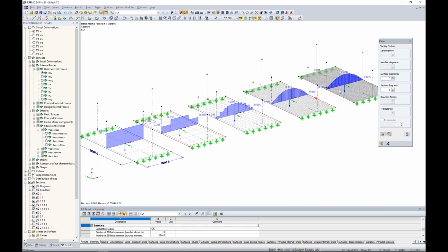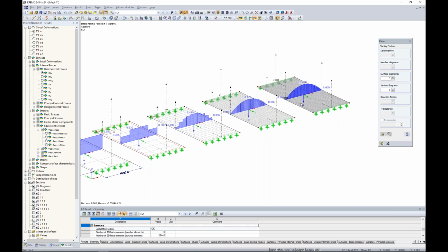So very little difference when we're looking at some of these surfaces towards the end here with an increase in FE mesh. So I would argue that maybe the second to the last, or possibly even the third to the last, just depending on your structure, is adequate for gaining those accurate results while not waiting forever for your solution to run.